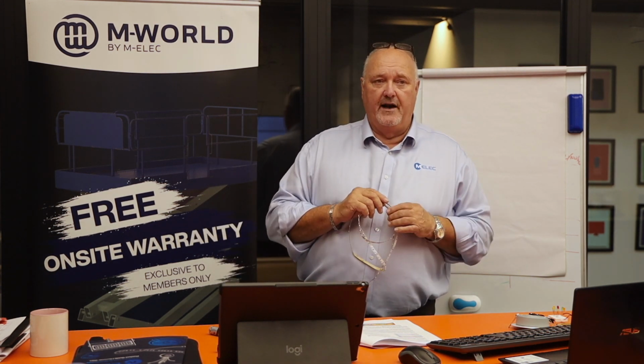Okay, the next thing to look at is dynamic tunable white, which is also called CCT. It's still non-addressable, but what that can do is take us on the range from warm white through neutral white to white, and vice versa. So it becomes a CCT. There's also multicolour non-addressable, which is our RGB and our RGBWs and things like that.